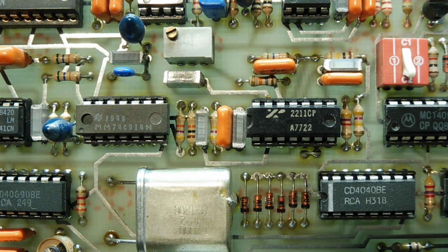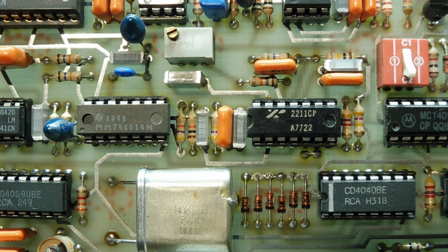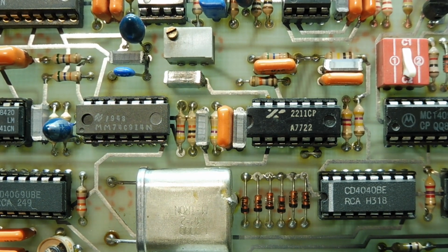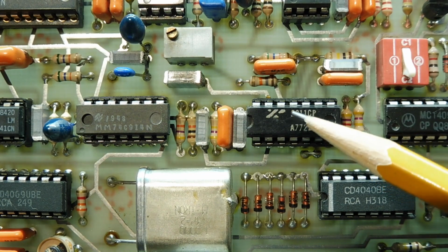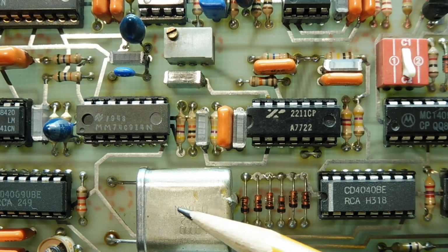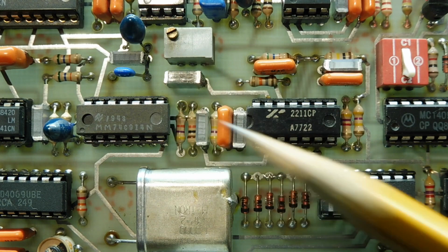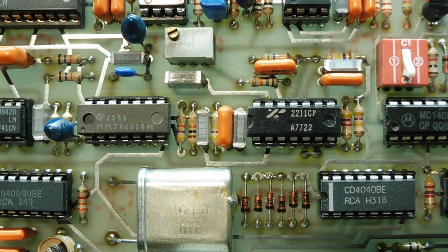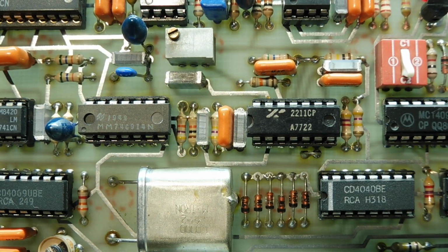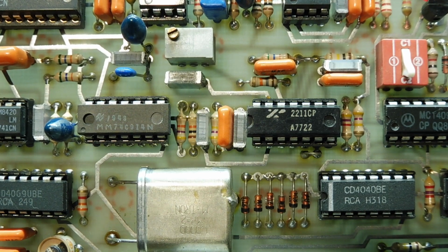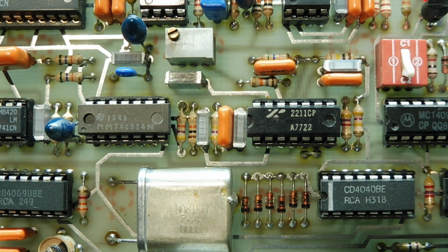Okay, now to decode an FSK signal. There are a couple of ways of doing it, and the one I'm using here is a phase lock loop. As you can see the IC here, I have a crystal oscillator for stability, and I got a tuning pot to tune the phase lock loop. So the phase lock loop locks onto the mark space frequencies, and the steering voltage to keep the phase lock loop in lock is the data output.